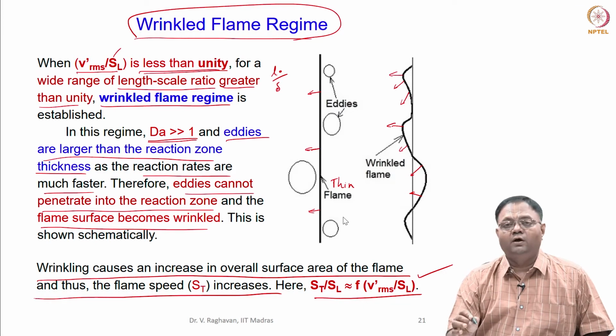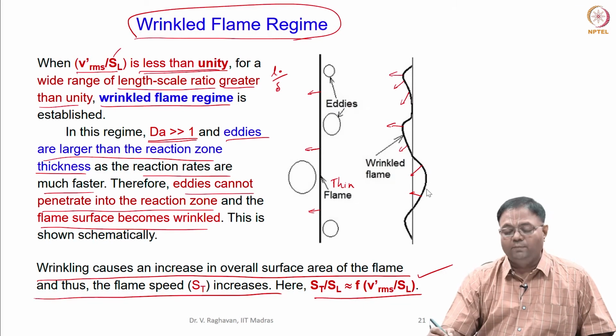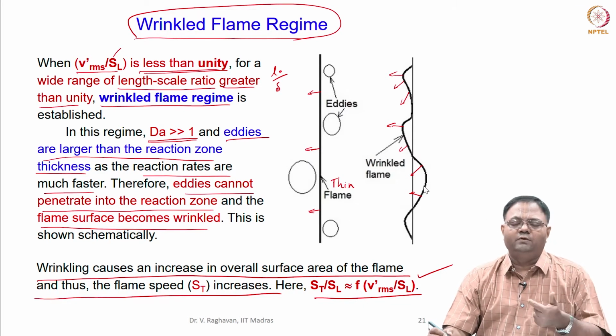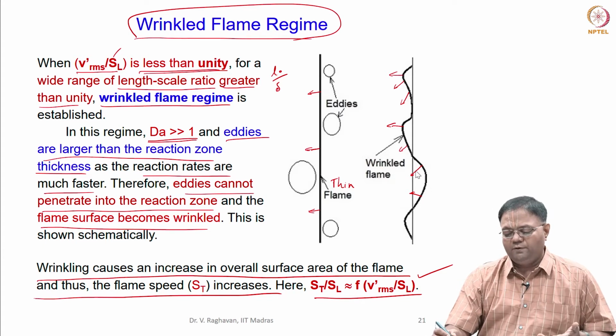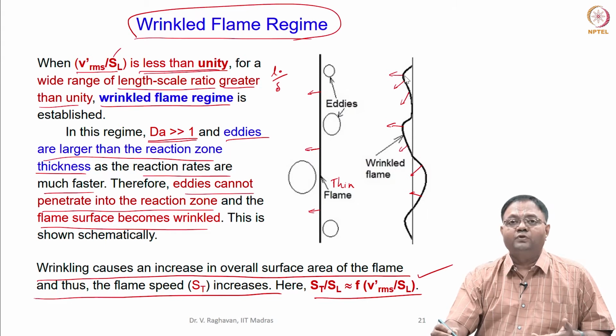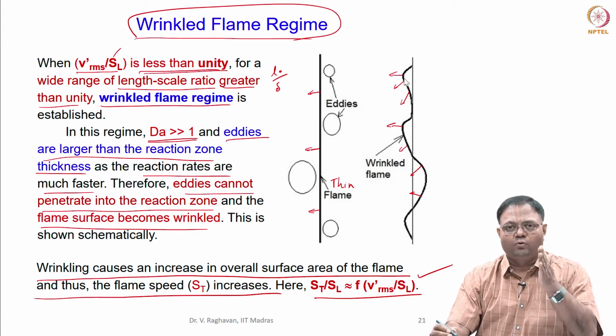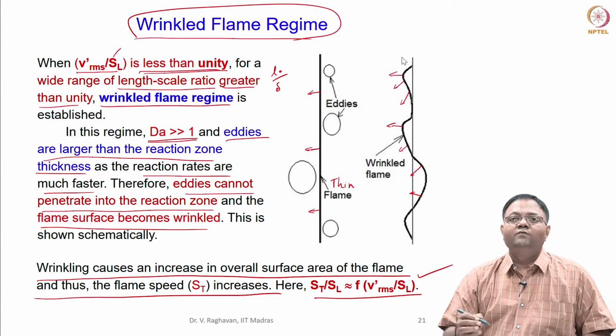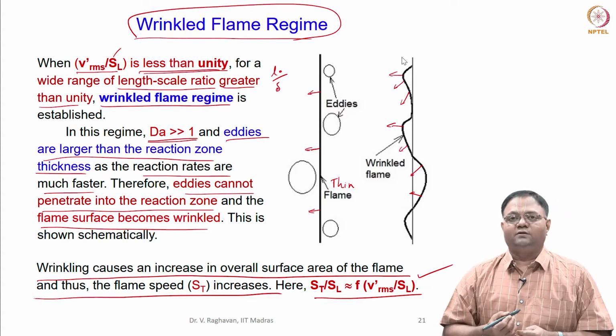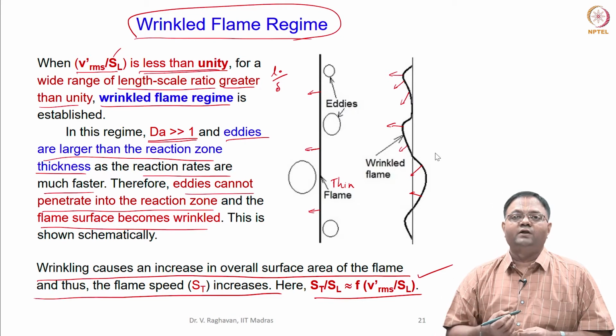You have to use chemistry to resolve this flame, and the interaction between the flow field and the chemistry. The chemistry is predicted only by the chemical kinetics, and when you resolve the flow field properly, you get the wrinkling, the increase in the surface area and so on.